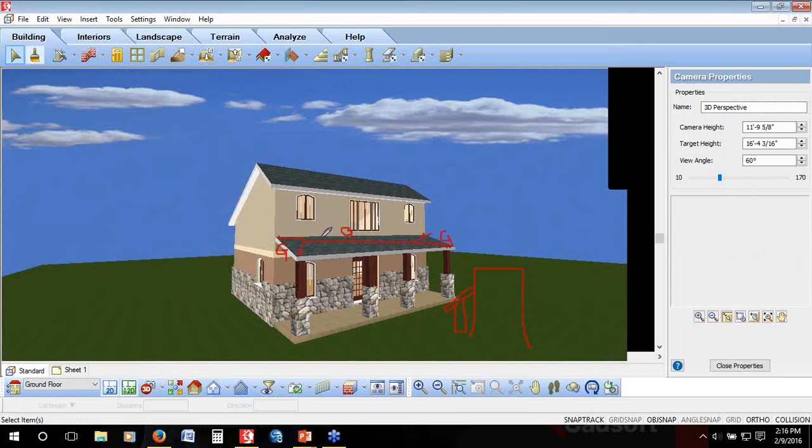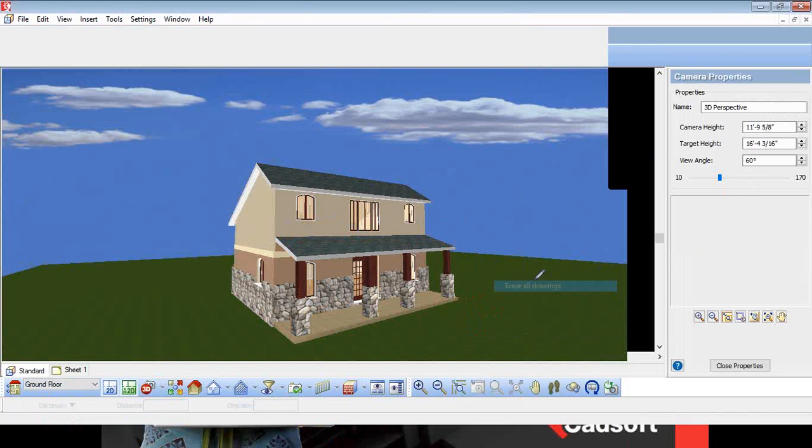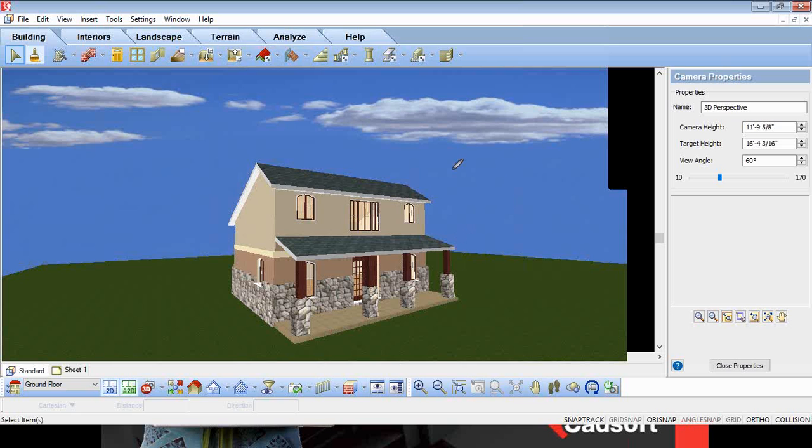So a gable beside a gable will automatically shed the roof. Gable beside gable, and I get a shed on the other side as well. Anywhere you wouldn't hang a gutter or an eaves trough, you're going to make into a gable end. Okay, so now we have our simple shed roof over the back, over the front porch.